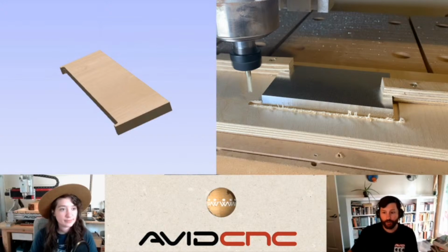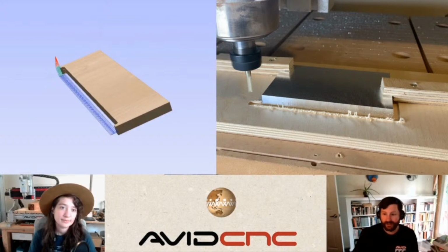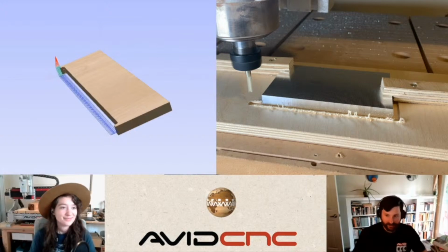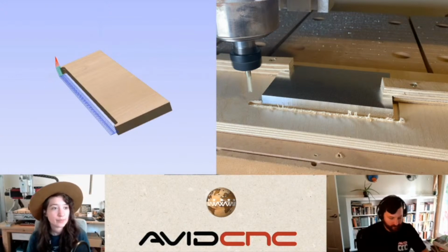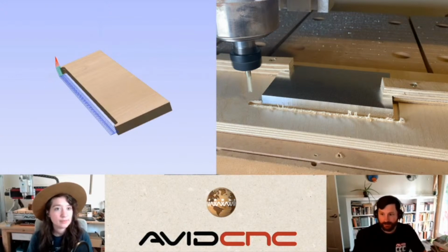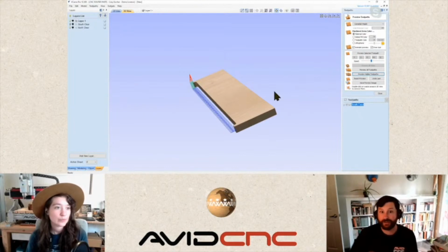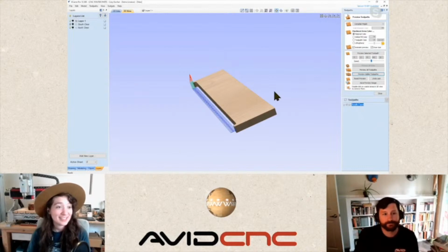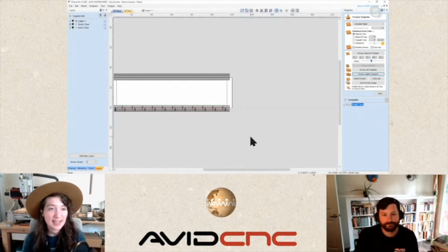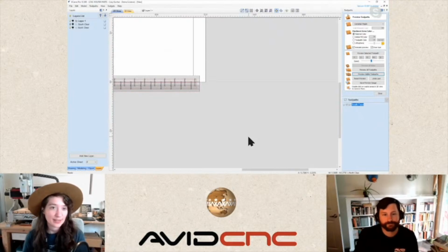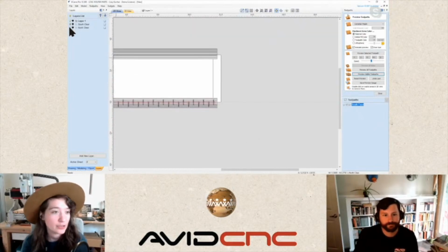Cool. One other feature that's really great here in VCarve is if we select all these tool paths, right click and click group visible, it puts them all together, and we can minimize and rename this to say south. And a little bit more cleanup to help us organize and make sure that we can do the south face and the north face very efficiently. Organization is really key when you're having this many tool paths. It's definitely a pretty easy thing to organize them by groups and makes it all easier to utilize and export later.